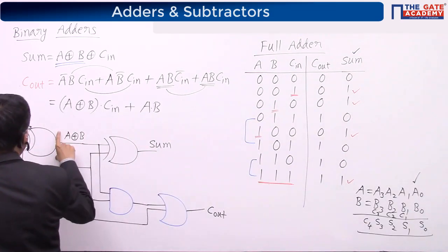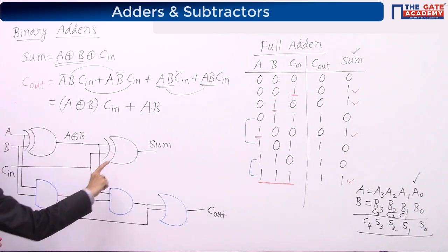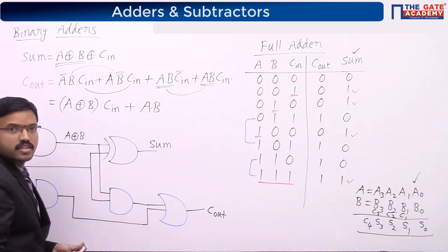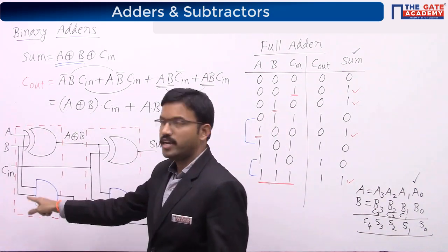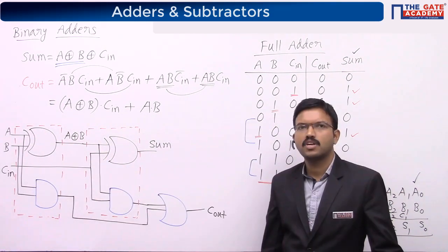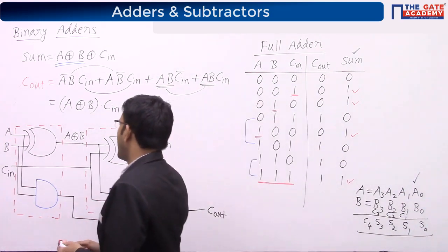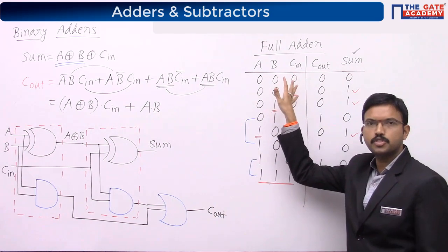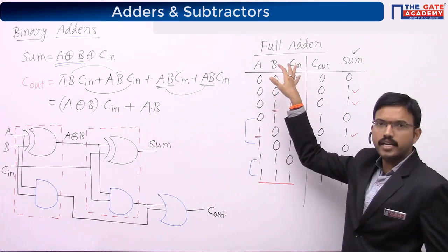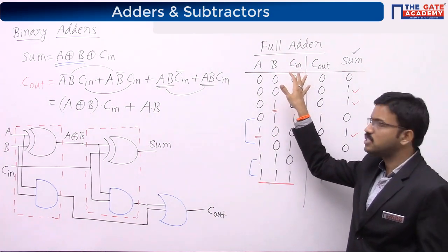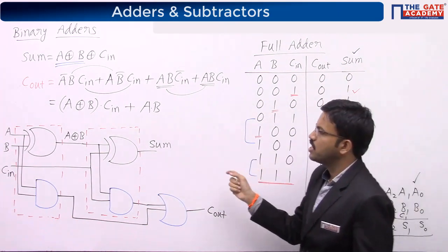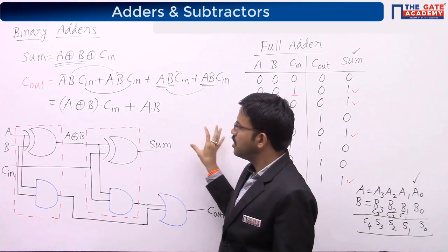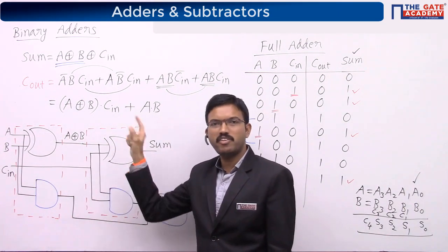Here we are having exclusive OR gate, AND gate, XOR gate, AND gate, OR gate. Just observe this dotted line. What is this circuit? Half adder, right? Actually, for implementing this particular adder, we are having 3 inputs. This particular adder performs addition of 3 single bits and produces 2 outputs. For implementing this adder, we require 2 adders of the previous type.